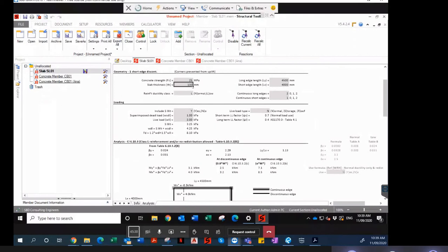Each reinforcement, 8 by 8, is 16 millimeters thick. So you've got 8 millimeters plus 8 top, which is 16, and the same thing happens at the bottom, so you take away minus 32. So you've only got 43 millimeters in between the reinforcement, which is nothing, isn't it? It's less than 2 inches.